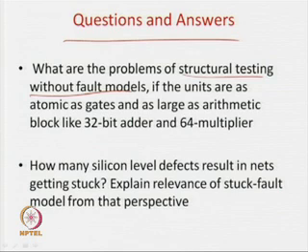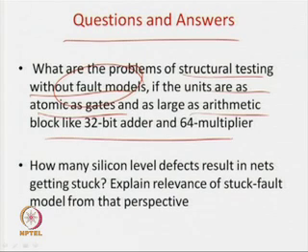And so, the question we are asking is, what is the problem of structural testing without fault models, if the units are gates as well as if the units are larger? One thing you can say about this is, we require a large number of flip flops, a large number of registers, a large number of extra pin outs. But you have to answer what the impact is. Without fault models, you require a lot of extra arrangement like pin outs, as I told you, gates, then 2:1 multiplexers, then registers and so forth.